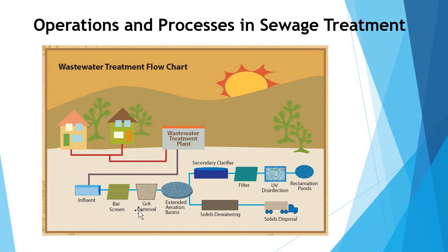And those particles which are not collected in the screen chamber and have more density are collected in the grit removal chamber, in which inorganic materials like soil, clay, stones, etc. are collected.